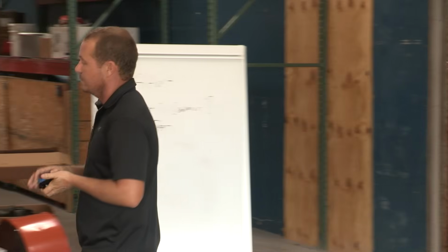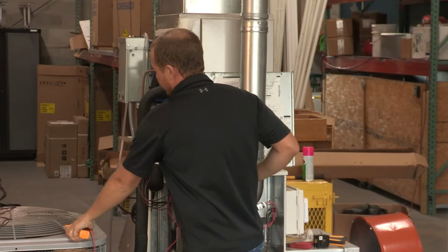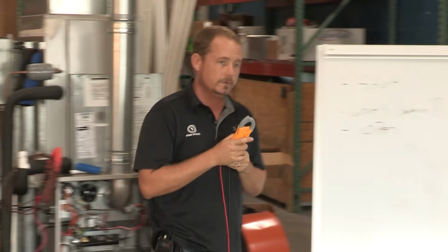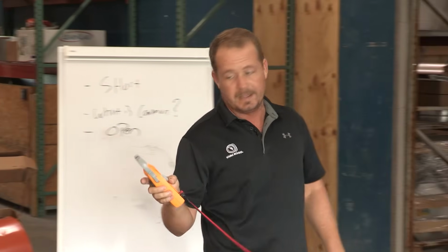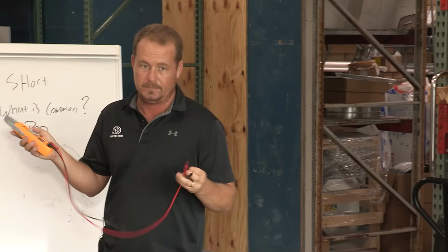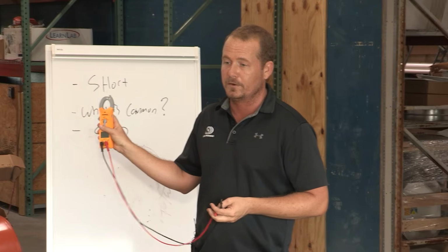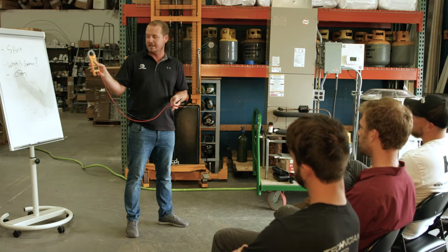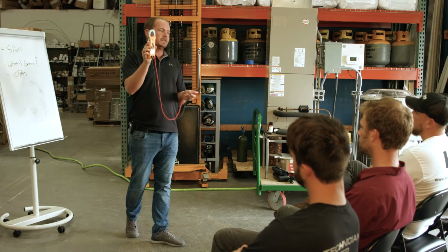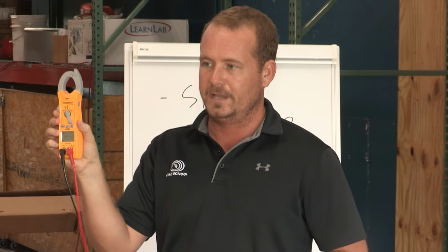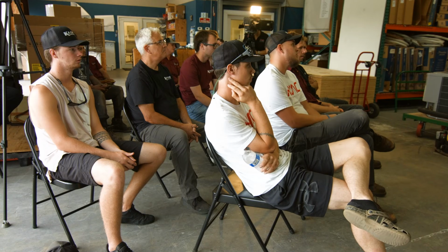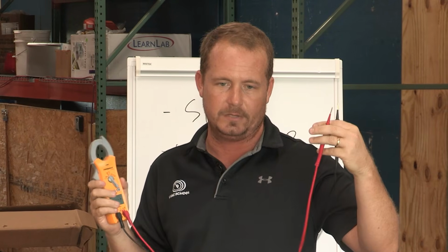Let's talk quickly about the meter for any of you who are new to the meter. The first thing I always want to see you do before you use a meter, this is just a really good habit to get into, is take your meter and put it on where? Ohm scale. Because what is a meter doing when you put it in ohm scale? Sending out voltage on the leads. Sending out current, right?